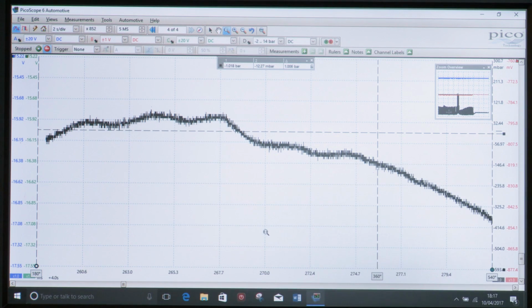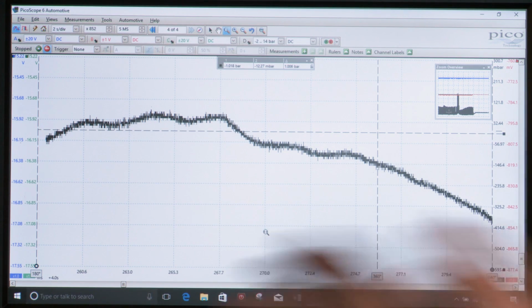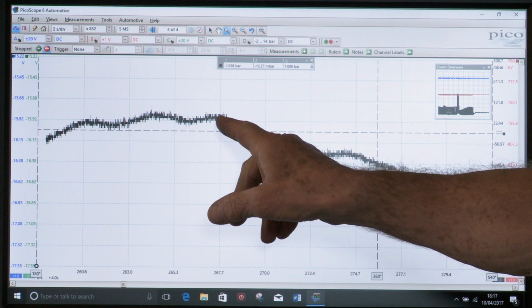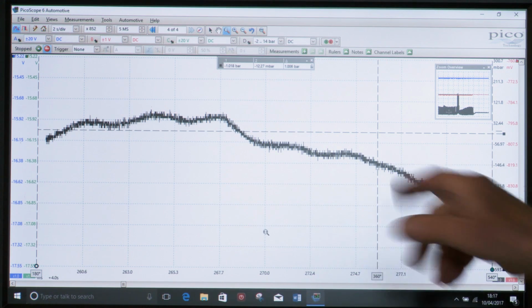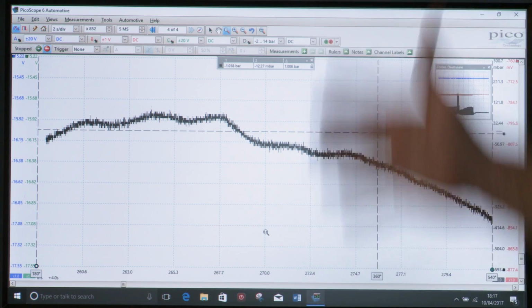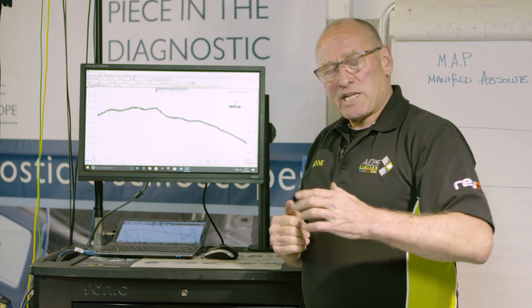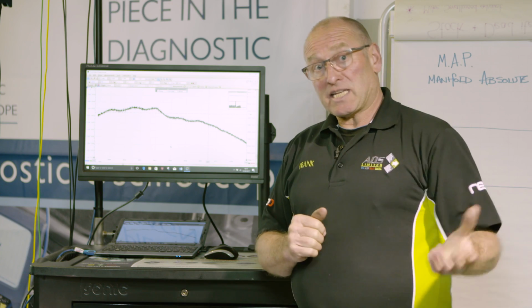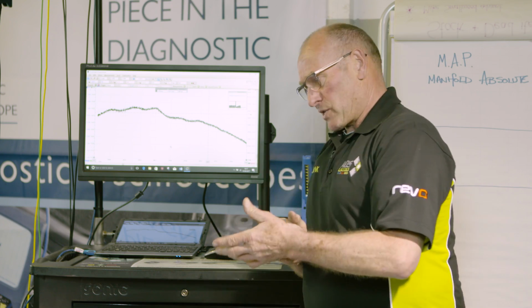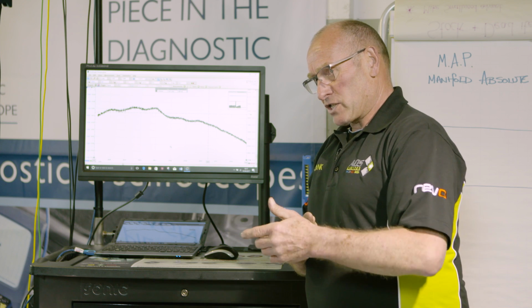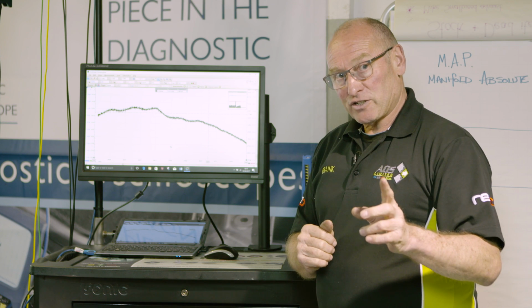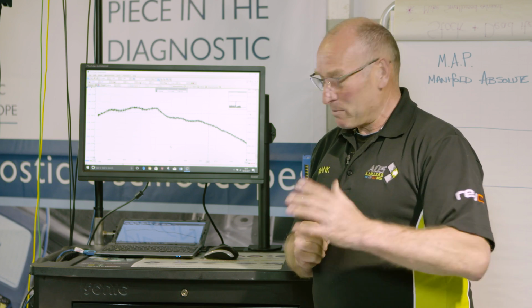There's a positive pressure in the exhaust stream. Gases are going into the exhaust, and suddenly it decides the pressure is going to drop again. Something's happened to cause this differential. Well, the only place you've got a differential is in the intake manifold with a closed throttle. So you've got a lower pressure. It's still a pressure, not a suction, not a vacuum.